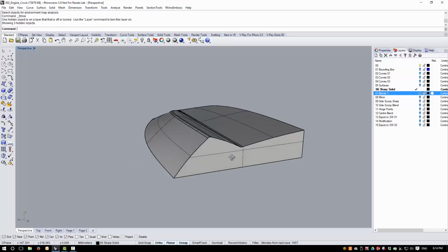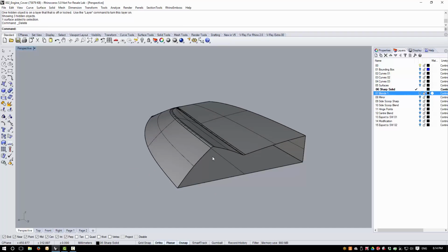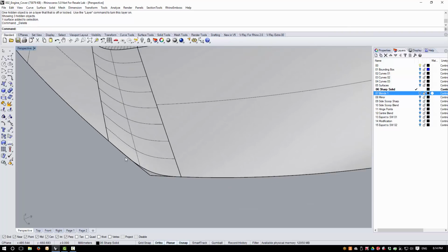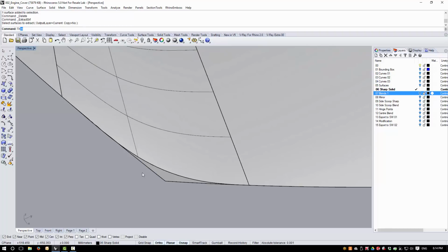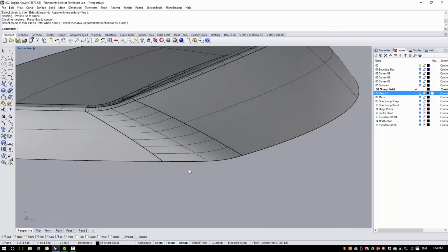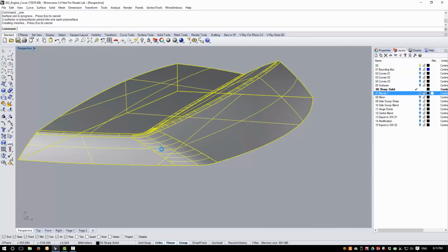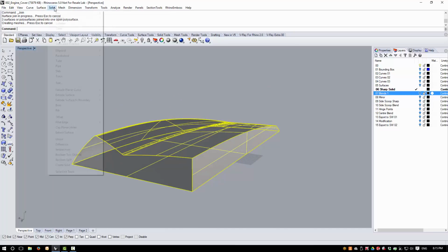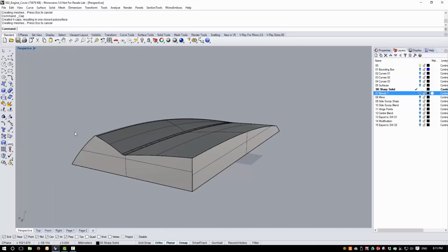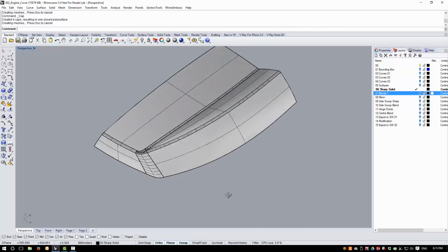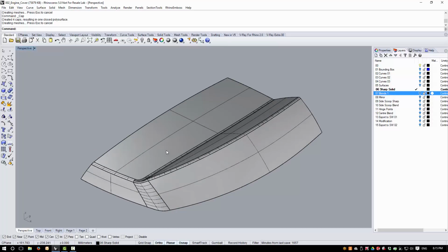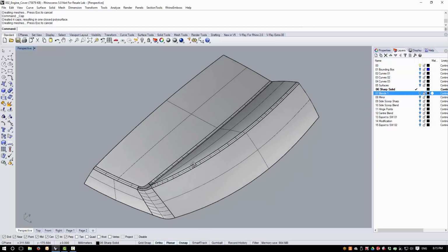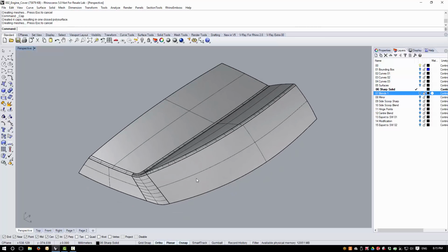show the surfaces that we've got hidden. I can remove that back and then I can trim away the corner here, join my geometry together and then cap the back of this. Okay, so we now have a closed poly surface, and we can now either move this downstream into SolidWorks, or we can add more detail to this.